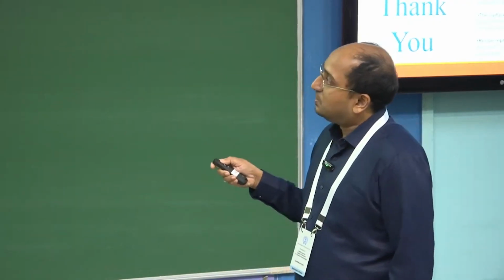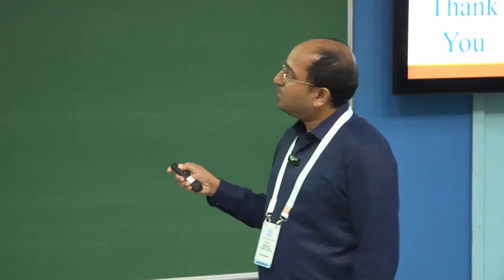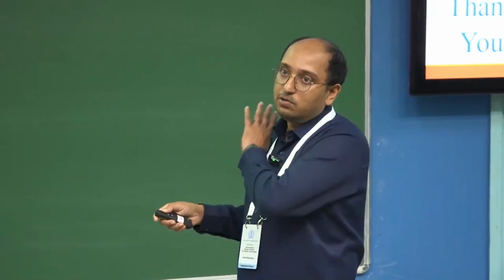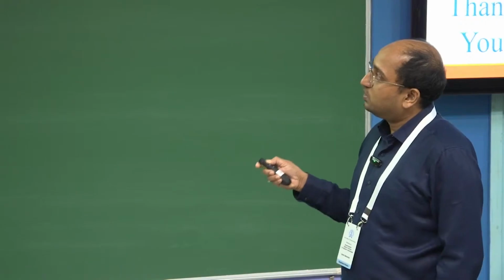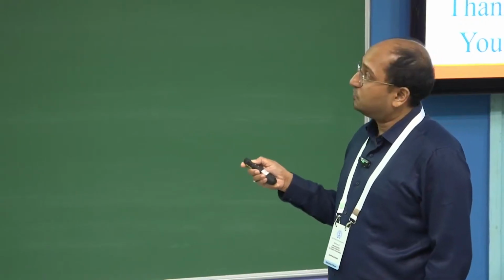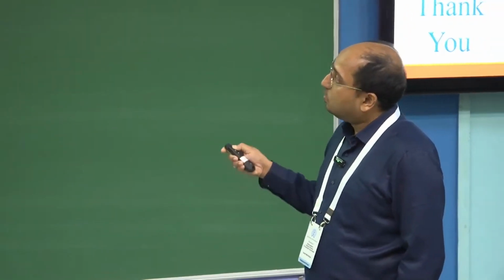And the devil lies in the surface. The surface is the killing factor. If we don't optimize the surface, if we mess up the surface, that will simply be repeated layer after layer, and we'll get a crappy material. So everything that has to do with epitaxy is to understand the surface. If we understand the surface, we can create reproducible epitaxial parameters for growth.